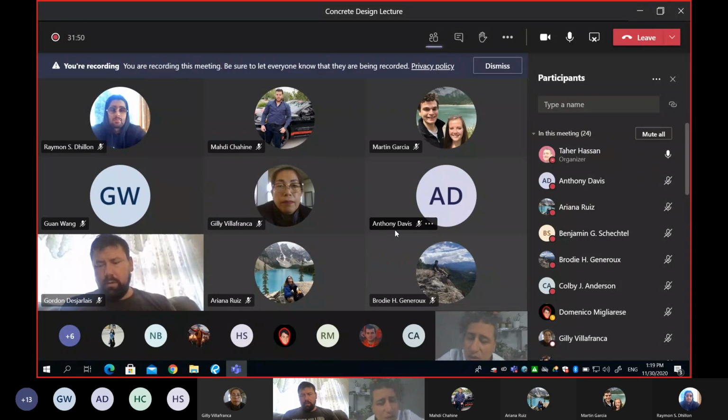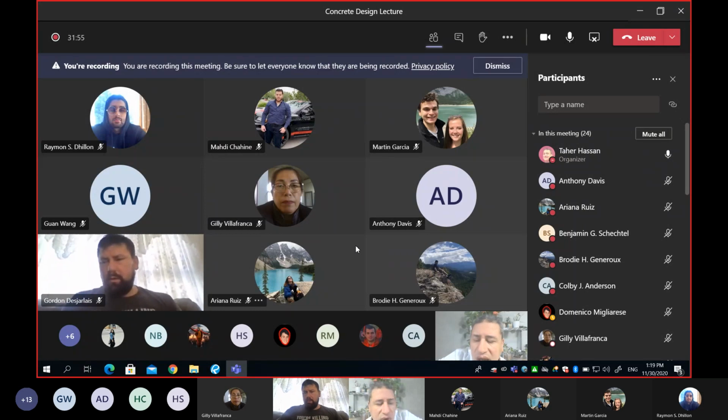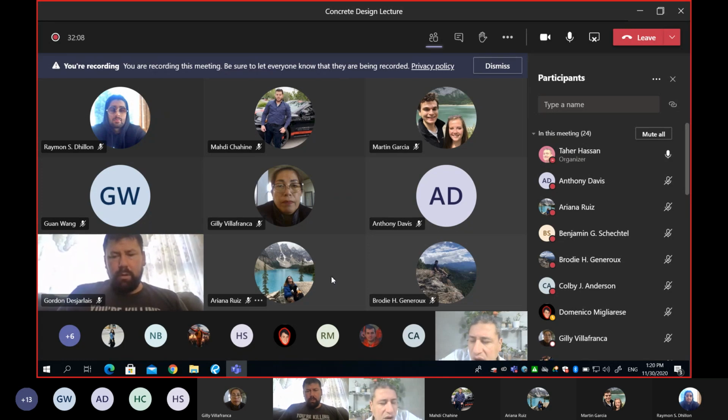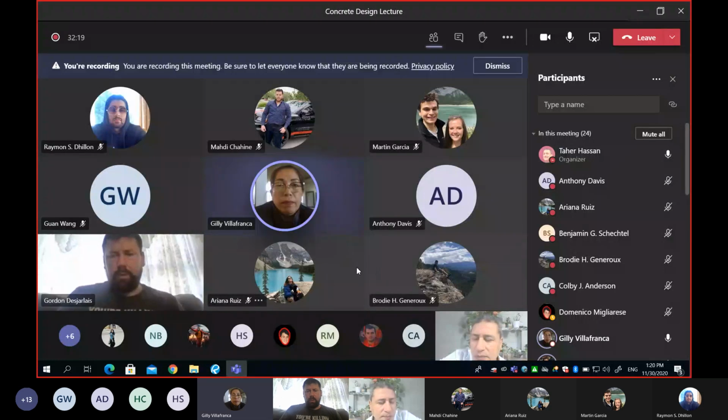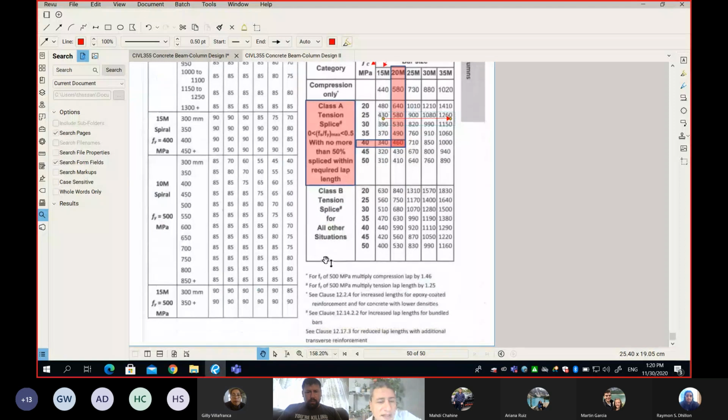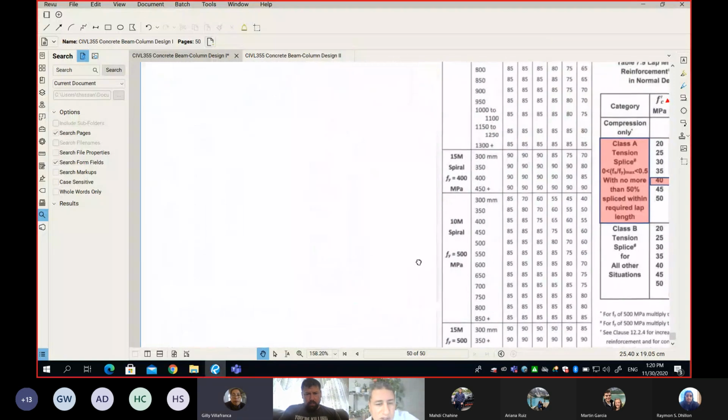And some of you may think, oh no, Tahir, stop. Listen, stop. Columns have a compressive force, which means all my rebar will be in compression. Do you agree with this statement? Columns have a gravity load, they are in compression, which means all the rebar in my column will be under compression. Would you agree? Can this be a general statement? The answer is no. What I said is not true, and I will try to convince you.